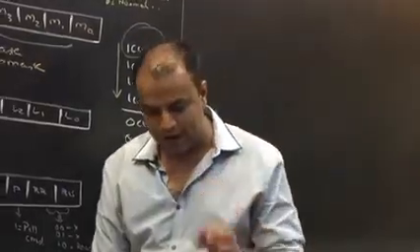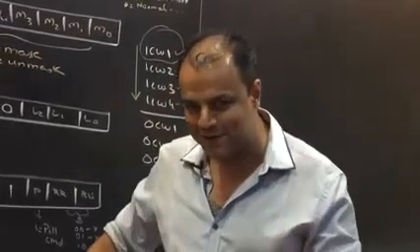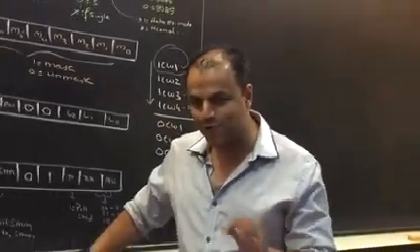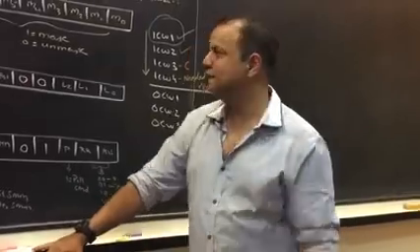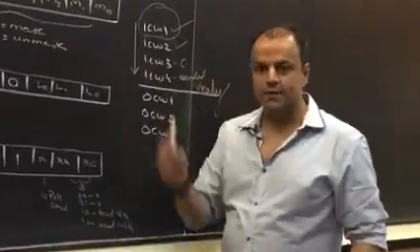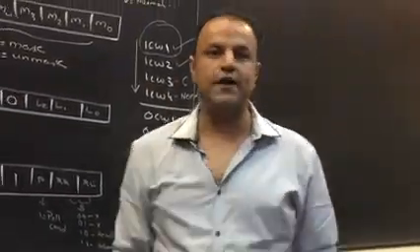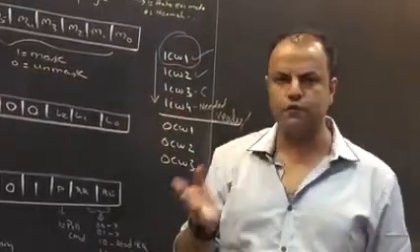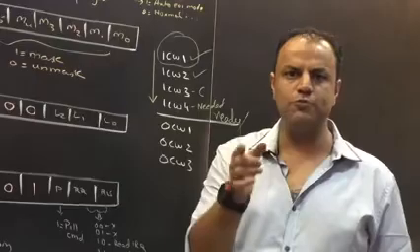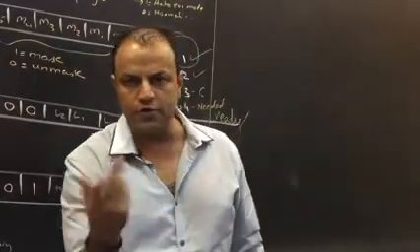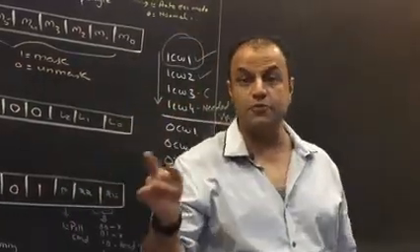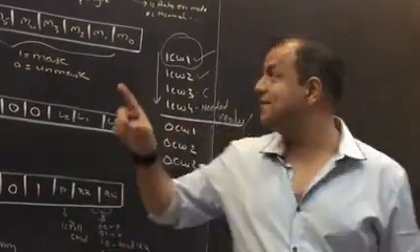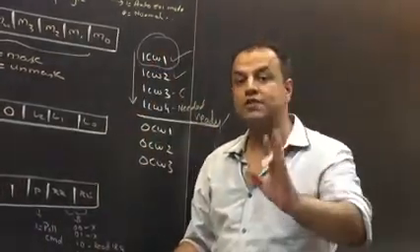I say for the last time, pay attention to everything I'm speaking. All of this will come back in a very big way. In ICW 1, you inform 8259 whether you intend to give ICW 3 and 4. You inform for each of them individually. Like I said, you may give 3 and not 4, or 4 and not 3, or both or none. Everything is possible. But what you tell in ICW 1 is what you have to stick by.